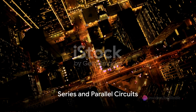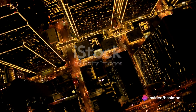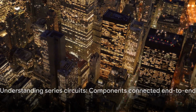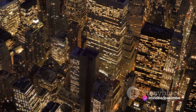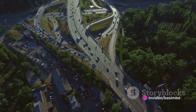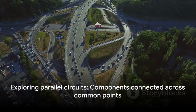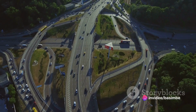Next, let's talk about series and parallel circuits. In a series circuit, components are connected end to end, forming a single path for current. Here, the same current flows through all components, and the total resistance is simply the sum of individual resistances. On the other hand, in a parallel circuit, components are connected across common points, offering multiple paths for current. In this case, the voltage across each component remains the same, and the total resistance is calculated differently.